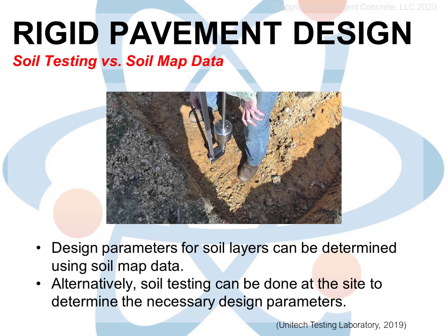A lot of times, though, it is not possible to perform a site-specific soil test using a soil drilling machine and running the soil samples through a lab to determine their characteristics, a process that can take a week or more. Using soil maps and classifications can be a quick and often reasonably accurate way to estimate the soil characteristics, at least for planning and estimating purposes. This method will be considered as adequate for purposes of this class.